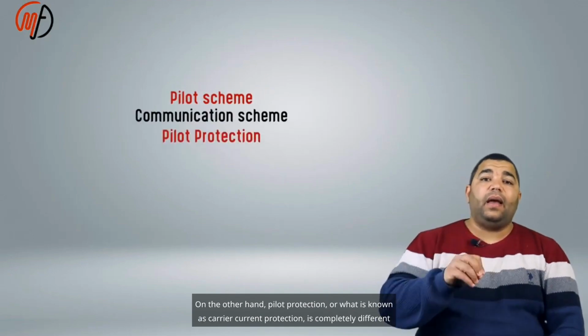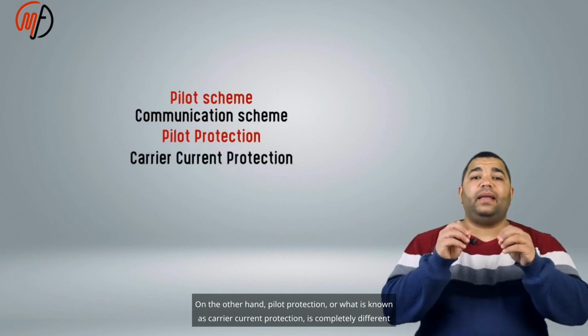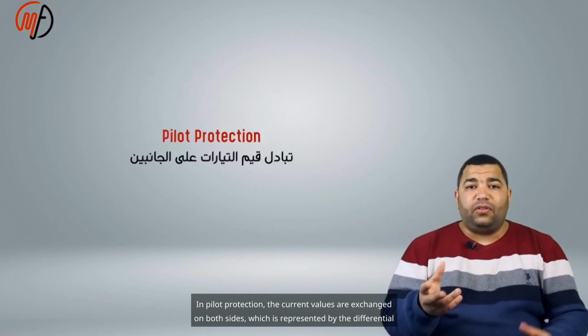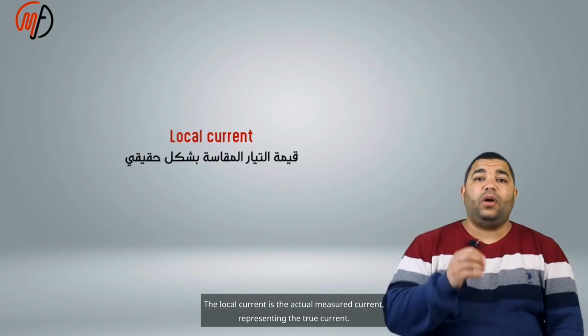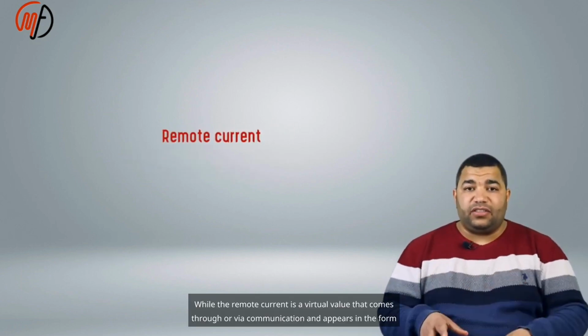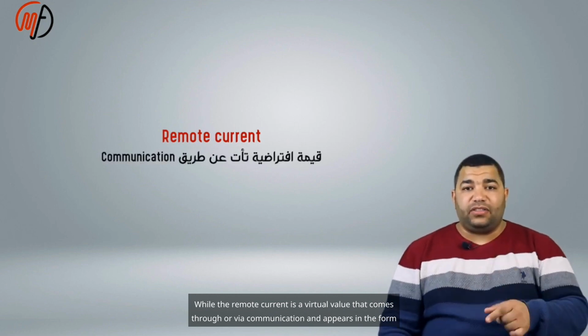On the other hand, pilot protection, or what is known as carrier current protection, is completely different. In pilot protection, the current values are exchanged on both sides, which is represented by the differential relay. The local current is the actual measured current, representing the true current, while the remote current is a virtual value that comes via communication and appears in the form of pulses.